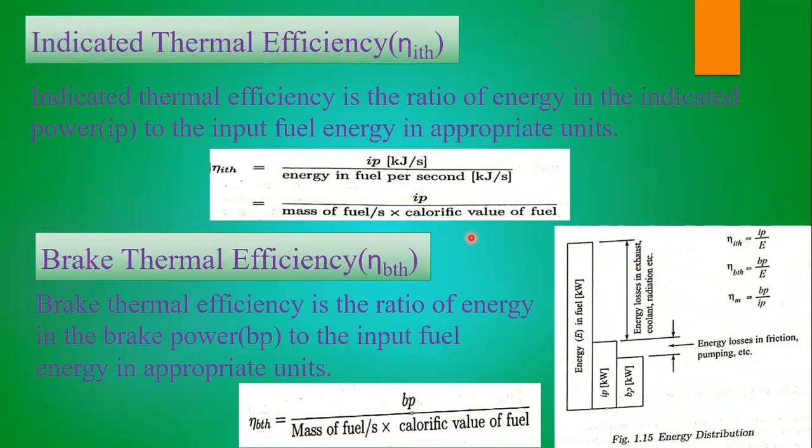Why? Because the fuel shouldn't reach its self-ignition temperature that easily, as there are chances the unburned mixture reaches its self-ignition temperature and creates knocking. So the petrol should have a high self-ignition temperature, which means the calorific value is going to be high.